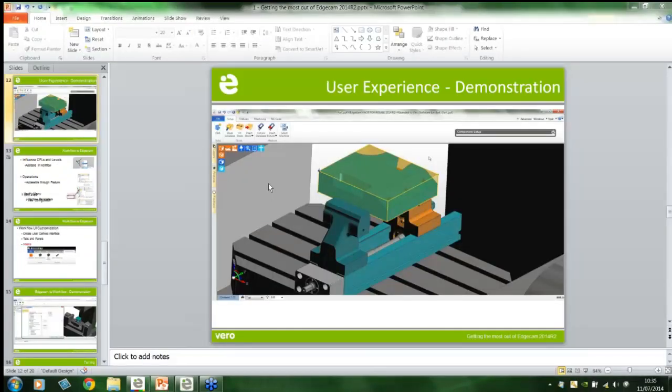Okay, so just got some questions. I won't answer them all. I'll say we'll maybe answer them towards the end of the session. But can you dimension the part to create a drawing? I guess that refers to the EWS. So you don't do any dimensioning at the moment. You obviously can do your constraining, but you can't create a paper drawing as you would do inside our part modeler. So if you need to do that, then I suggest you go down the part modeler route.